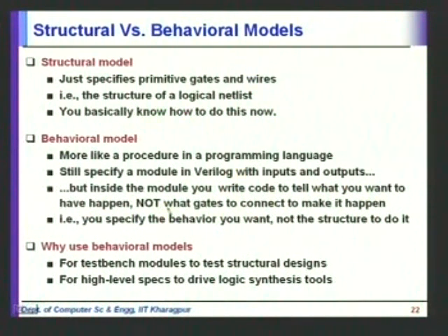So when you are writing out gates, you are almost synthesizing the circuit. You are almost giving it in the circuit form. Whereas in the behavioral model, you are going to specify it in the algorithm form, and you will expect the synthesizer to take that and actually generate a circuit which does what this behavioral model does. Right.